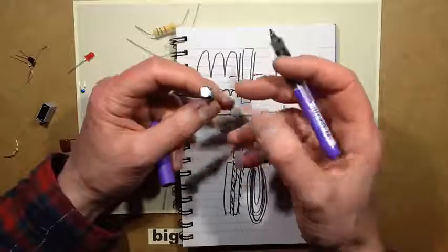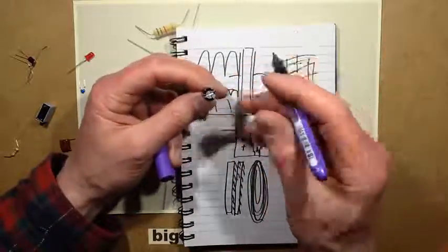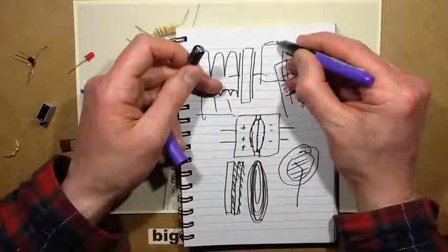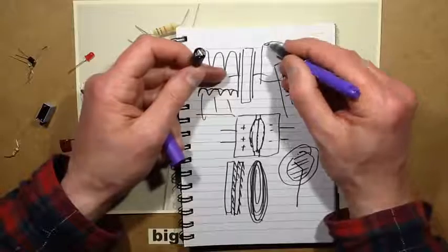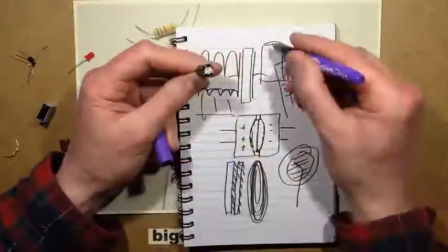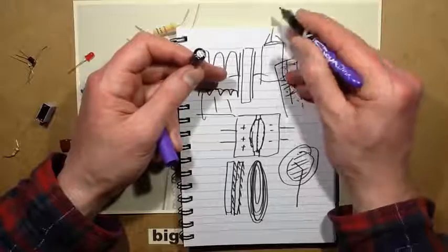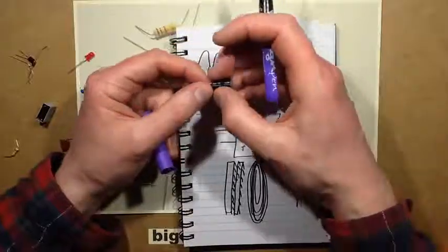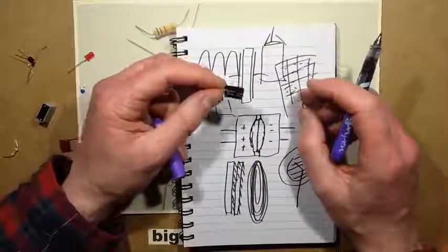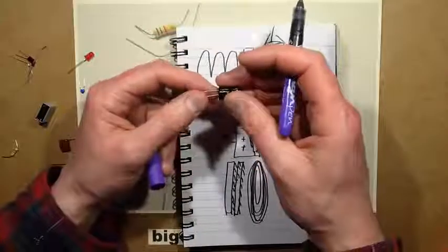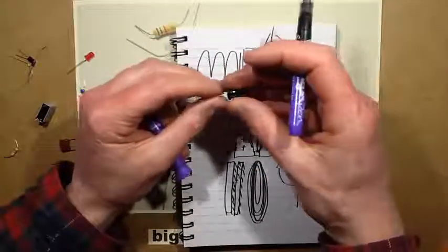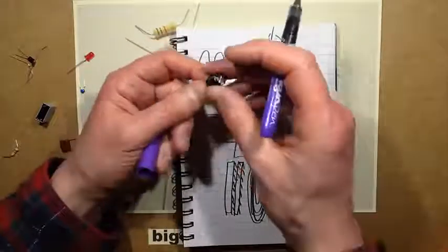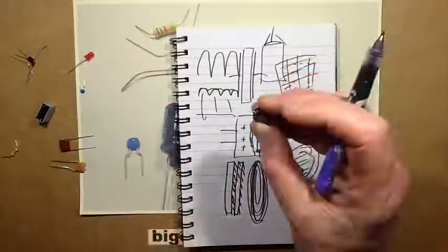Basically it turns into a sort of resistor, and it boils the electrolyte. And when that happens, the top will bulge up, if you looked at it from the side. But if it goes too far, that X that's etched onto the top will split open, and it will vent out the top. The other option, if it doesn't do that, is sometimes it blows the whole can off, and it just makes a mess. It gives out a vapour of the electrolyte, which is slightly caustic. It can unravel the foil across the room. It can go off with enough force to actually cause injury if it hits you. So you have to be kind of careful with electrolytic capacitors.